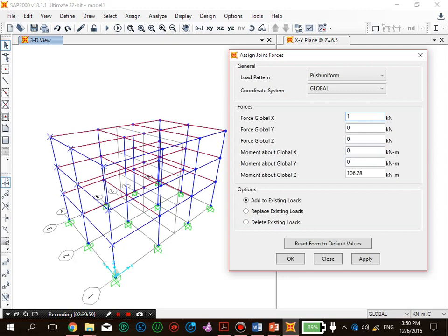If you want to apply distributed load along the columns, you can. You could do that as well. But in my case, I apply joint load because I have already defined a diaphragm for the joints. So the joints will more or less move together. So it's not really important. Okay, but in your case, it gives more exact results. It's okay, it's not a problem.